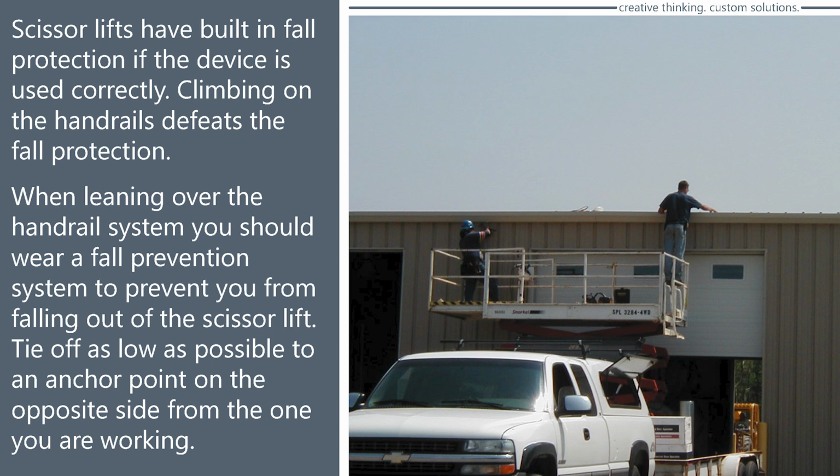If you go above the fall protection system, he needs to be tied off somewhere that he cannot fall and hit the ground, of course. But the problem we have here is a lot of people want to tie off to the side rail. And if you fall off the side rail, some of this equipment, based upon how high they are, you can actually cause these to topple over. You don't want that to happen.